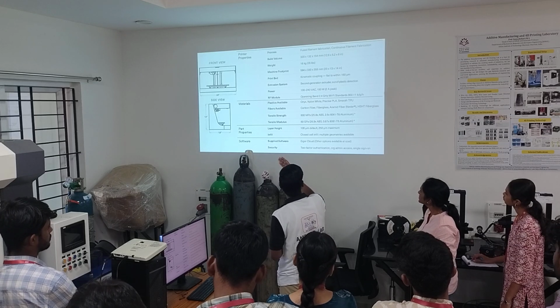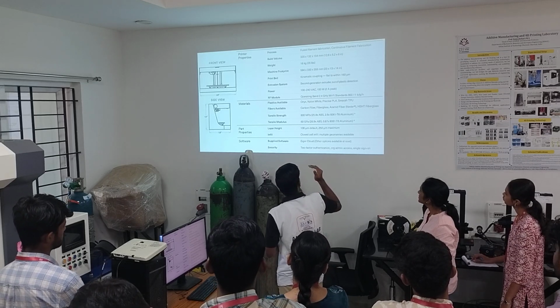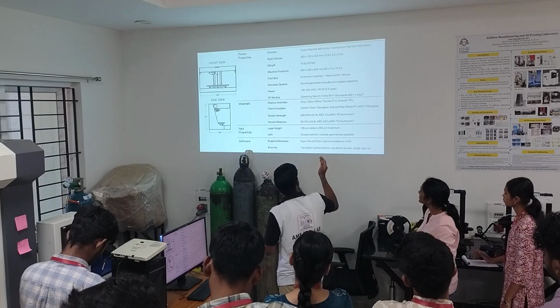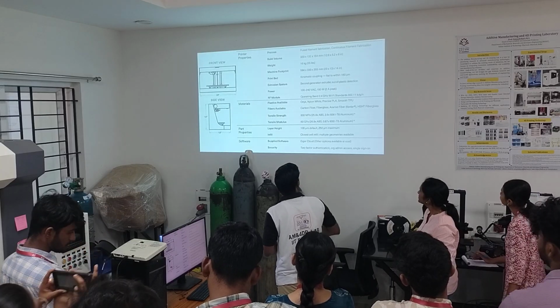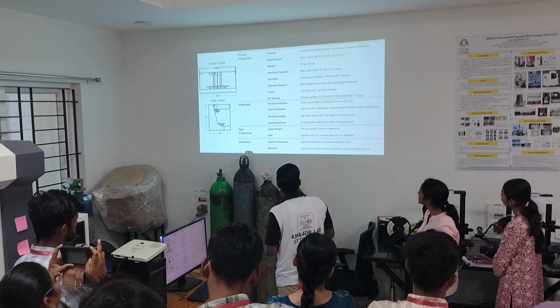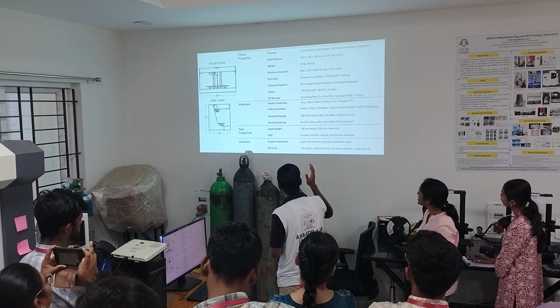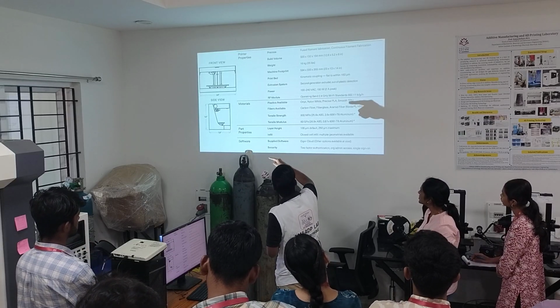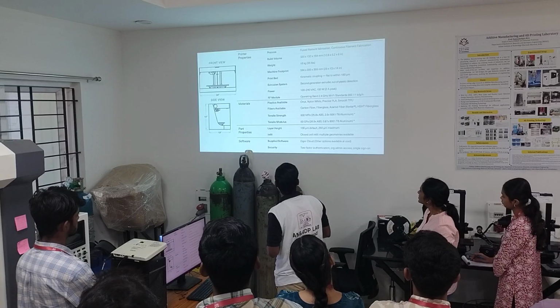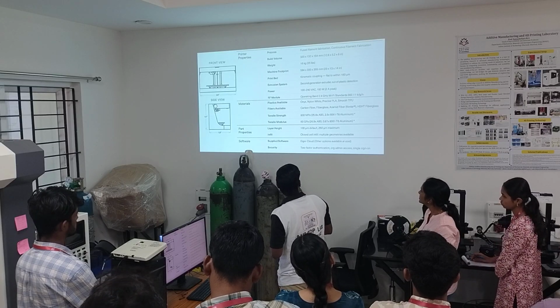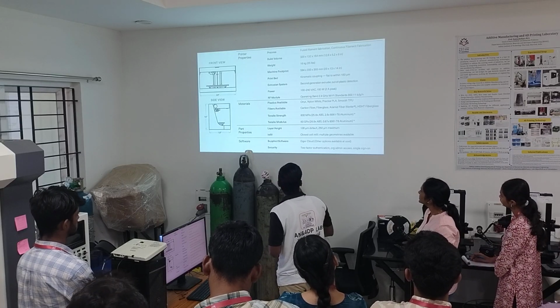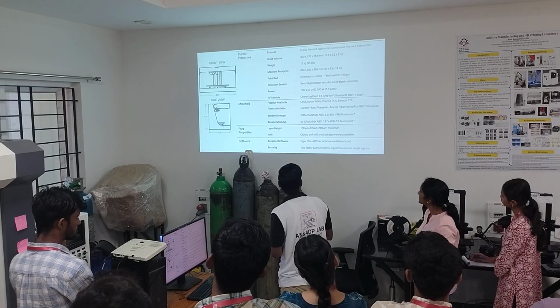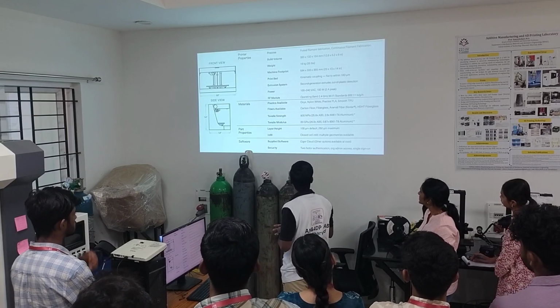Fibers, we have carbon fiber, fiberglass, aramid fibers, high strength, high temperature fiberglass, also normal fiberglass. So this kind of fibers as well as the plastic can be used here. Plastic basically means the matrix material. Minimum layer height can be 100 microns, and maximum it can be 250.